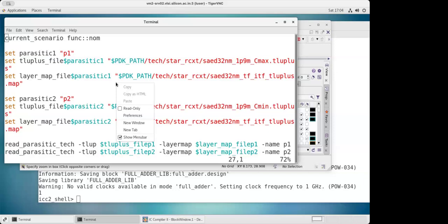So we are talking about the precision. I think all of you remember, we studied it in the 7th, 8th, that scaling precision part. So that basically comes as a part of variation, foundry variation. Now if your dimensions are going to change, C equals epsilon A by D, overlapping area, your capacitance is going to change.